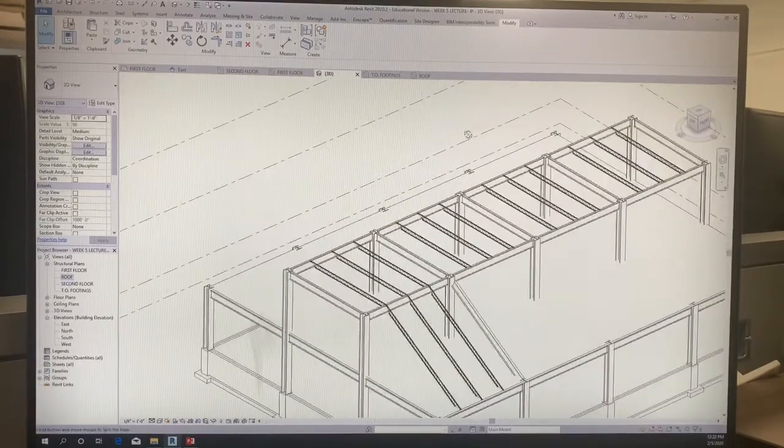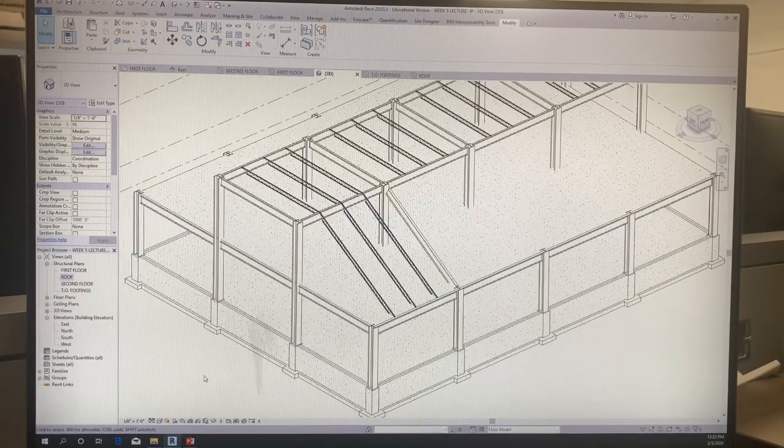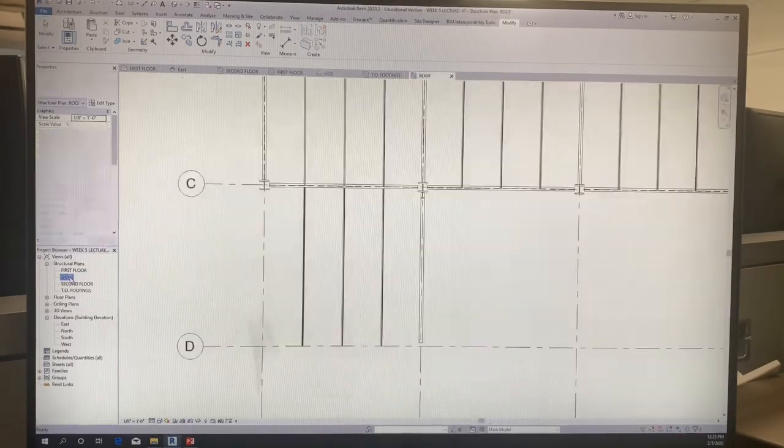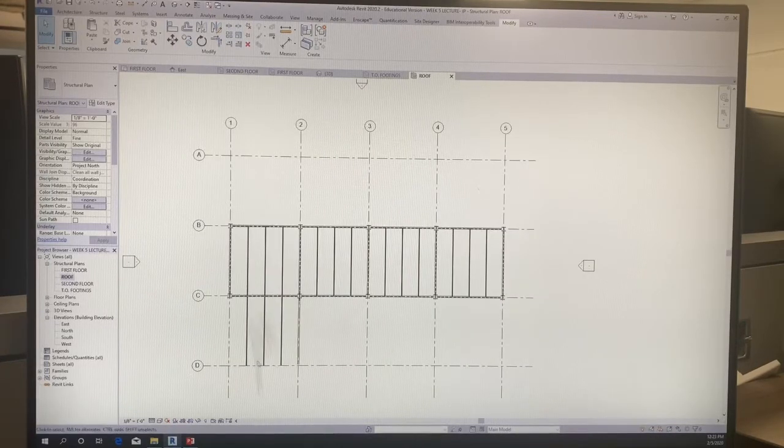Alright. So same thing, if I wanted to do it on that side, I could copy that over. Okay, but let me now show you how to put in the roofs here. So remember, we don't have to drop any of these beams down because roofs travel upwards. So all I want to do here, we'll start on the roof level. We're just going to put a roof along here, and then we're going to put a sloped roof along here, or a shed roof along here.